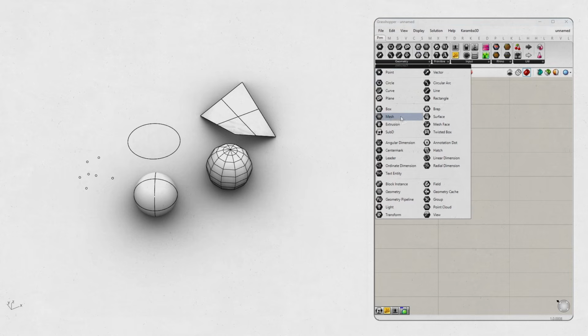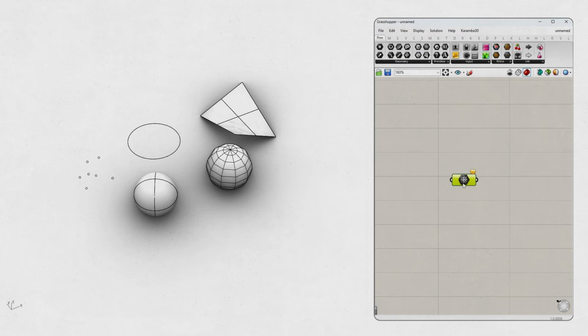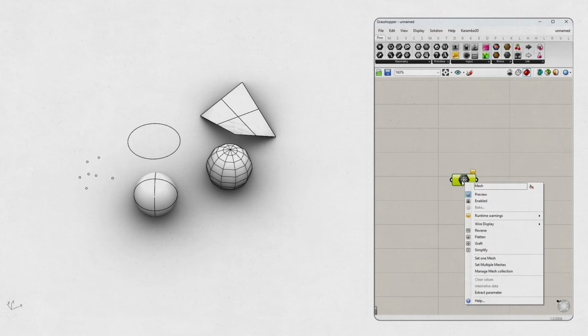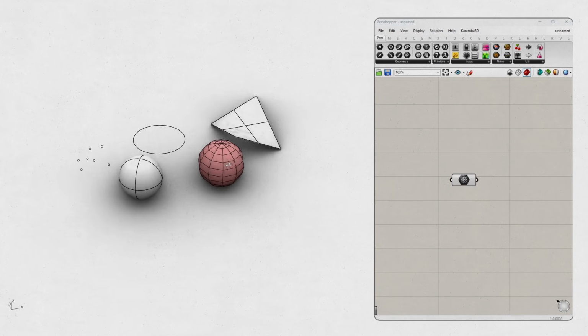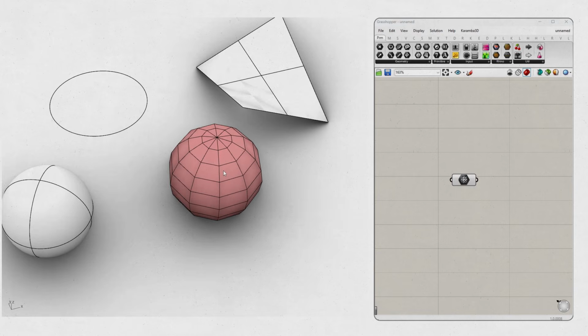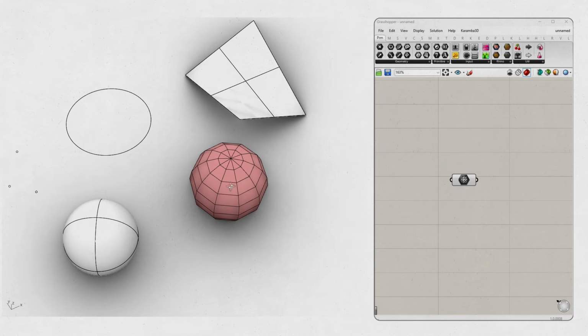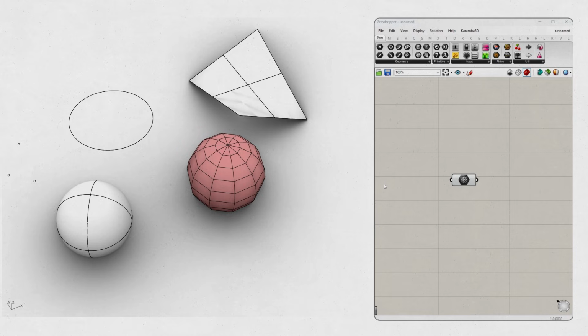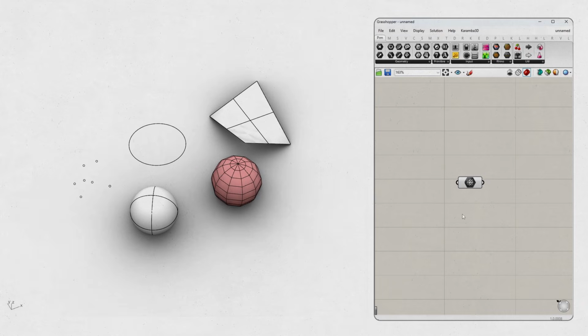All right, so here's the deal with mesh, right? It's all about those polygon geometries. You see, the mesh component is for models made up of polygons, especially when you've imported OBJ or FBX files. Or maybe the model came from another software. Or, get this, you might have even created a mesh yourself using Weaverbird or Rhino tools. Meshes process faster, but they don't quite have the precision of NURBS. So, yeah, you get speed, but you trade off some accuracy.